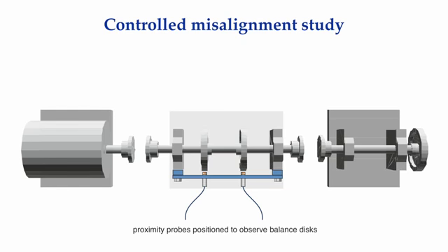Another question that was being discussed at that time was, does it take more energy to run a drive system misaligned compared to aligned? So, at each step of the experiment, I also measured the current draw on the motor using a clamp-on ammeter. The test was fairly simple.